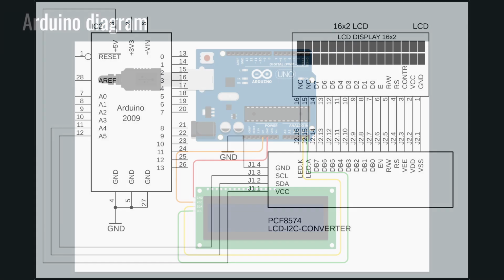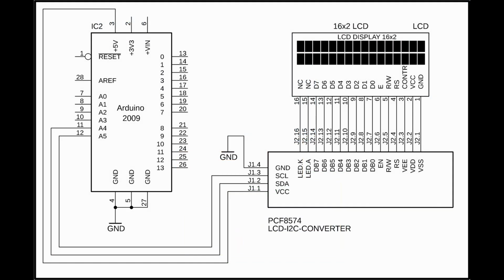As you can see, we are using an LCD screen with an I2C module. This module will allow us to simplify the connection with the LCD screen so that we can focus on the code development. Basically, it works as an intermediary between the LCD and the Arduino.